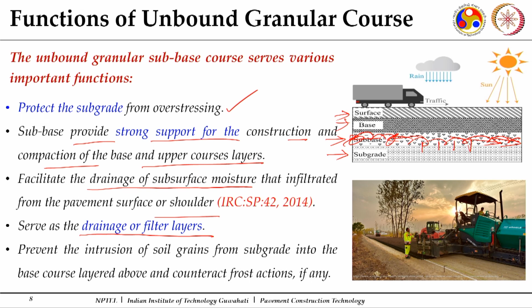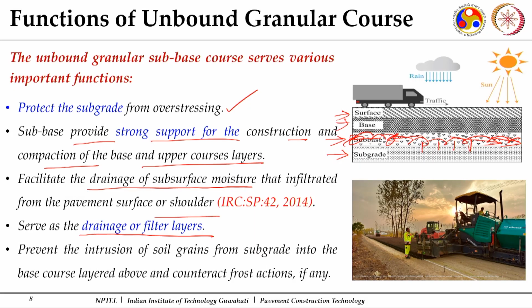That layer which allows the movement of water forms your filtration layer, and the layer which is specifically designed for drainage forms your drainage layer, because it has a high permeability. So, it can serve multiple purposes. That is why different types of gradations of granular courses are recommended. When we discussed in the last lecture, we mentioned MORTH recommends 6 gradations for granular sub-base courses. The reason for these 6 gradations is that different gradations are used for different specific purposes.